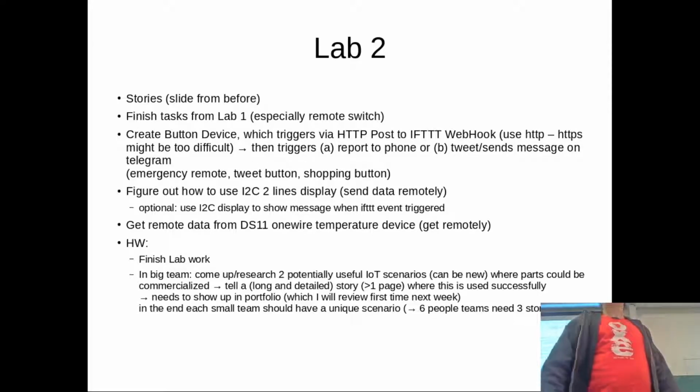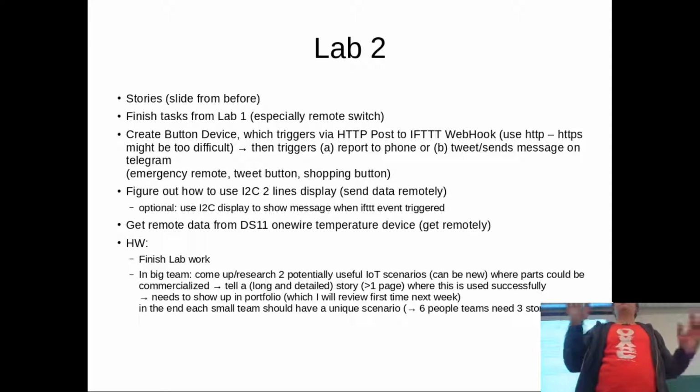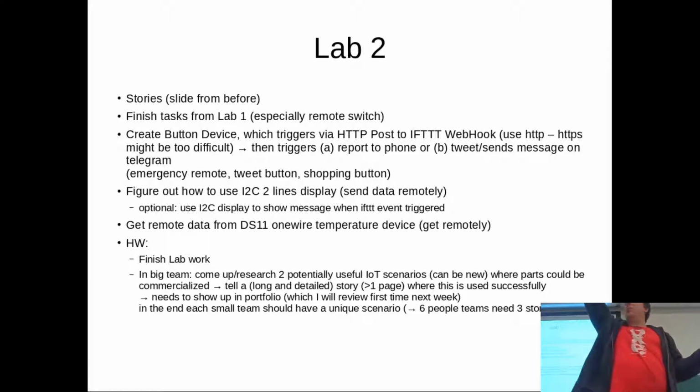Any favorites? As I mentioned, I always told some groups that I2C is one of my favorite buses because it's low active. I don't know if you all figured out or read about what low active is. Basically the 1 is ground, so it pulls the voltage level down. Usually we have high active, so if the voltage is up, it's a 1. If the voltage is low, it's a 0.